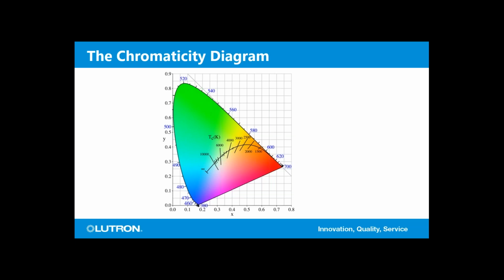Coming from the lower right, arcing across that line, you get increased correlated color temperature, and whichever line you're closest to is how we determine what correlated color temperature you actually are. The line is known as the black body locus, which is a black body up until about 5,000, and then after 5,000, that's how we calculate or reference daylight.